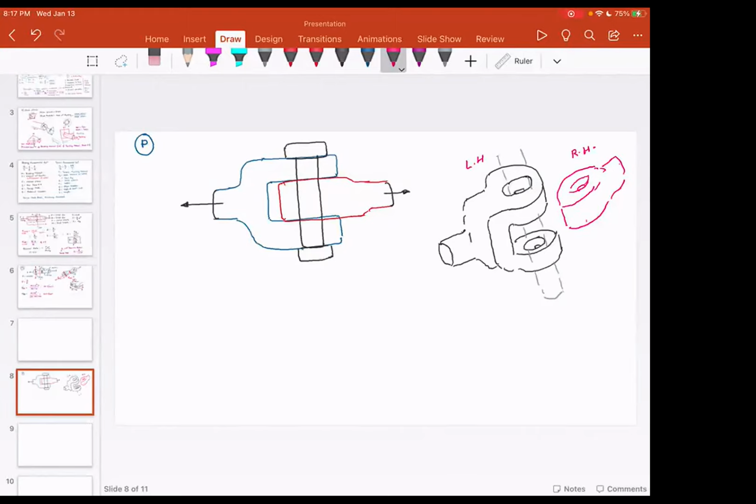Now in this configuration you have 80 kilonewton of load. This joint is similar to a knuckle joint. We will study the design of the knuckle joints in detail. So you have this 80 kilonewton of load that is transmitted. Now I want you to visualize that this is a pin joint. There is a reason that we are applying a tensile load, because if this joint is not properly constrained, the hinge or the pin, the joint would rotate about the pin. So that's why we are applying the 80 kilonewton of tensile loading.